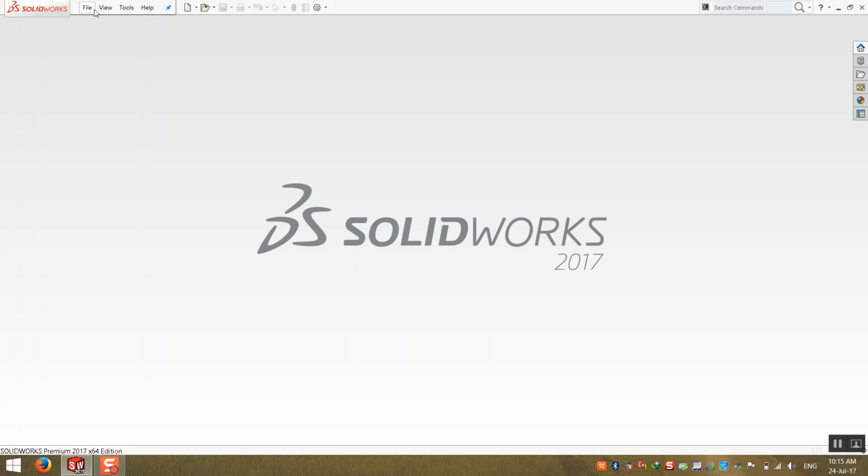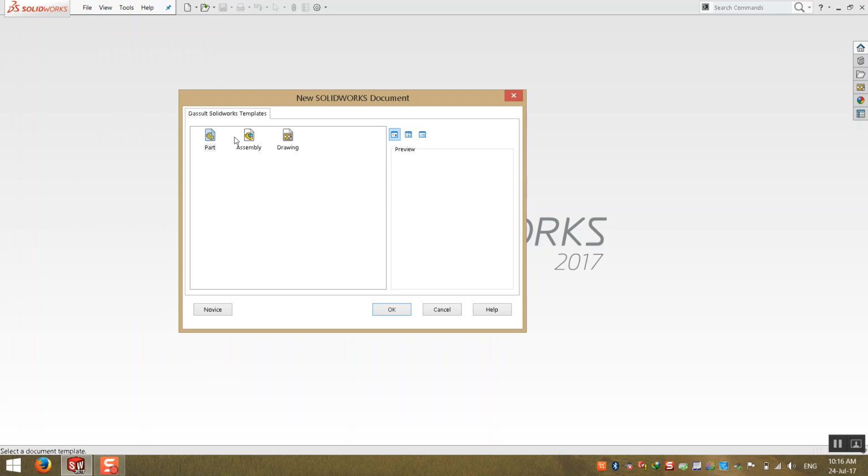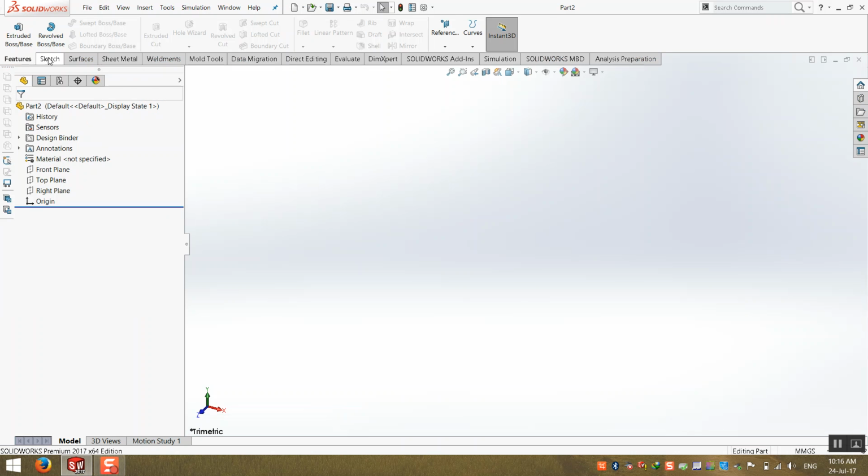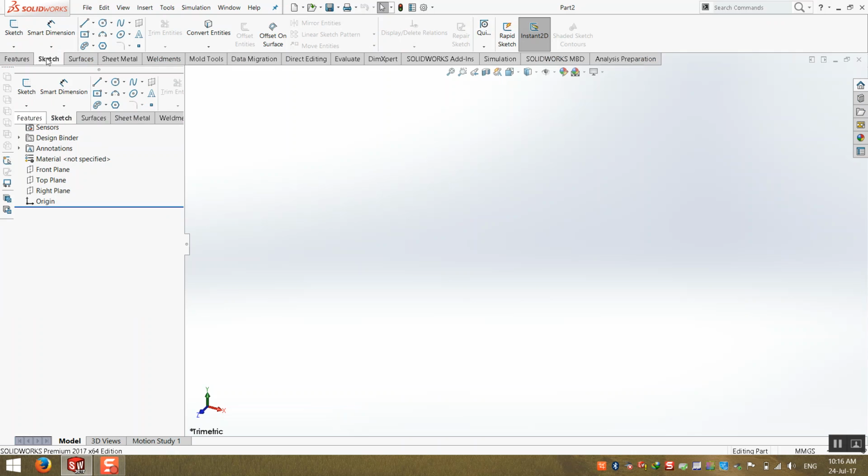Draw one circle. Okay, I will offset this 5 cm. Now, if I want to get the smart dimension, how will I get this 5? Now your friend asks how, if you have a circle with another one inner, and you have a specific dimension here. He needs to know how to get the dimension from this edge to this edge with smart dimension.